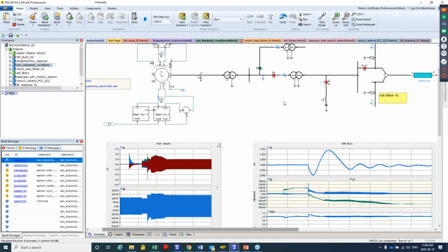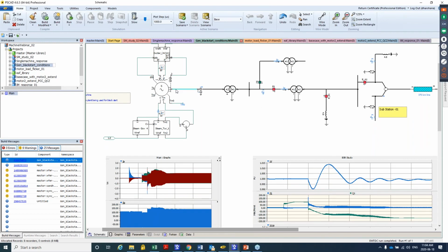So step by step, first, can I energize the transformer without tripping the settings of the generator? Because normally you don't do this. Normally you would energize the transformer from the system side and synchronize from the generator's low voltage side. But under black start, it's different, and your protection may not have been set up to account for that condition.